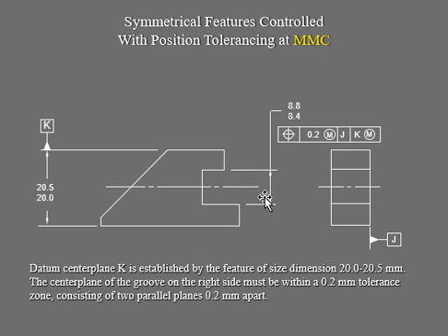And our plane is right there, your datum center plane K, which is right here. This is our datum plane, and the other one is J, and you can see it in the other side view. You can spot this one from the front view. You can see the inclined surface from the front view, but you will also be able to see it from the side view. So make sure you review your MET 101, engineering drawing principles.